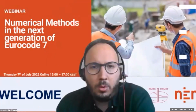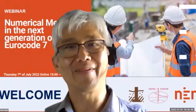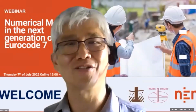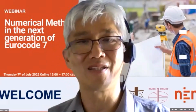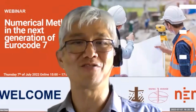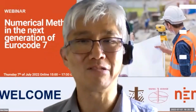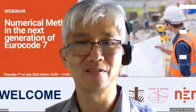But most of those tools, they drive the system to failure, right? The phi C reduction. Yes, they keep doing it. But the problem is, what does the soil model do? That is critical. It's not only that they drive it to failure, but you need to understand, in the process of driving it to failure, what the actual calculations are that it's doing in the background.